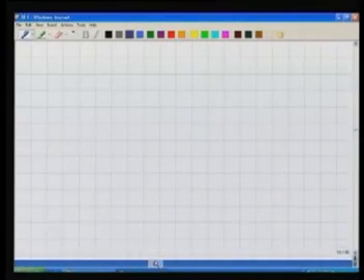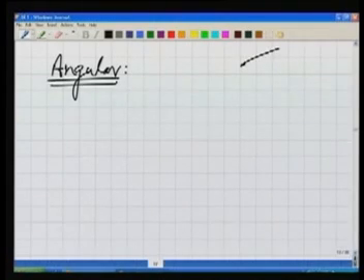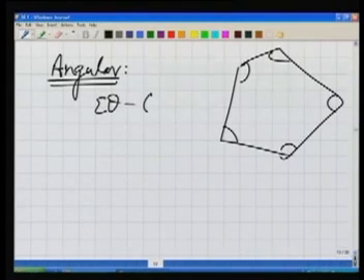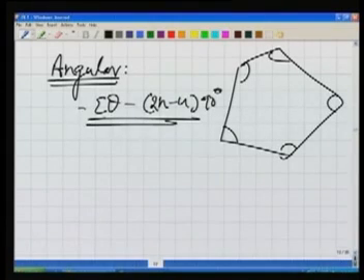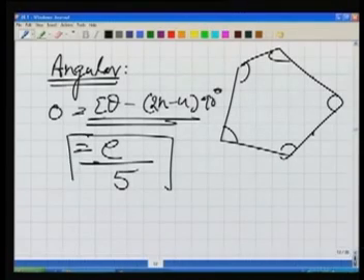However, now what are the sources of error? We have seen in a traverse we may have angular error. So what we can do for a traverse, we can adjust the angles. For the sum of internal angles, sigma theta minus (2n minus 4) times 90 should be equal to 0. If it is not equal to 0, rather it is equal to some error value, this error can be distributed depending on how many lines there are, 1, 2, 3, 4, 5. So that's the value of the correction to each angle.